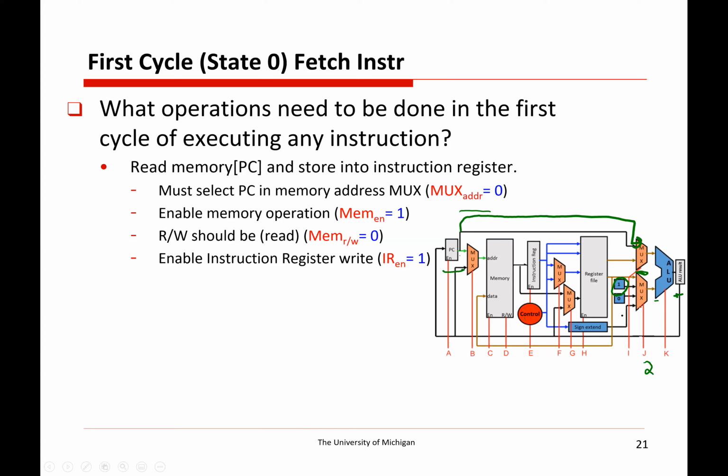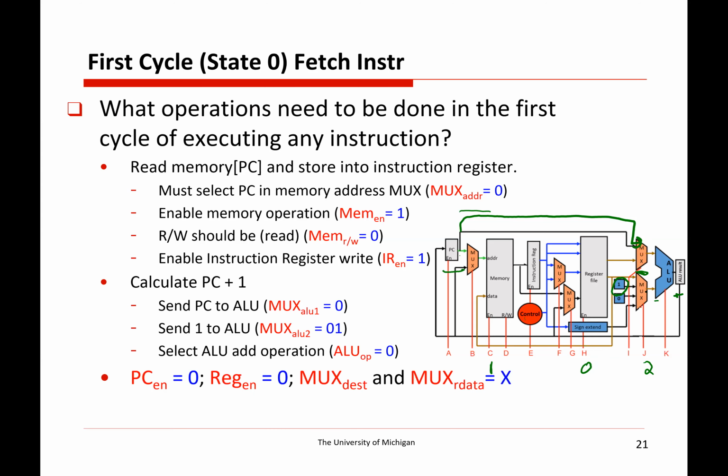So in order to get this to work, we're not updating the PC right now, so that's not going to be enabled. But we are using memory, so memory gets enabled. We're not using the register file, so that's not enabled. We need to select the top input from this mux. So the top mux is going to be 0, or just 0 because it's a single select input. The bottom mux we're using 1, the hard-coded 1 value. So we'll do 0, 1 for that mux input.